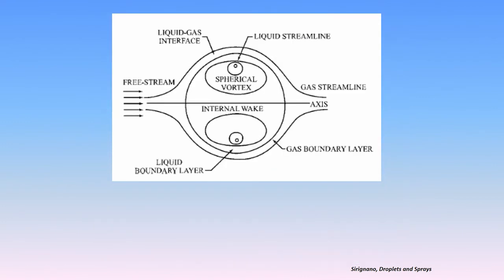And lastly, if you want to solve for the vortex method, then there is this spherical vortex that you have to solve within the droplet along with the free stream, and you have to take into account not only just the liquid conduction equation, but you have to write the full Navier-Stokes equation in the liquid phase.